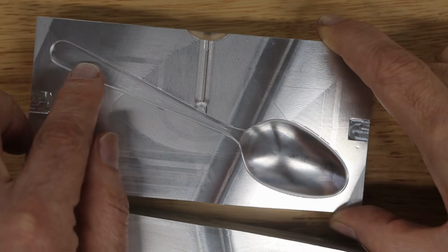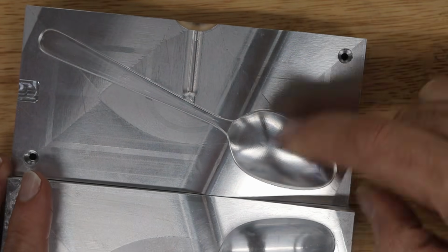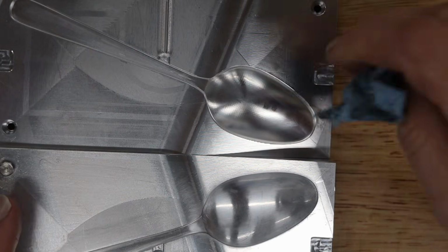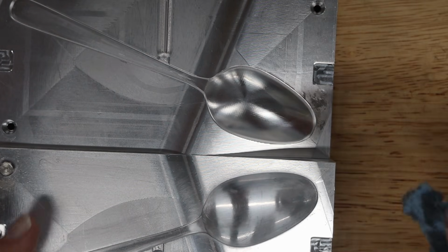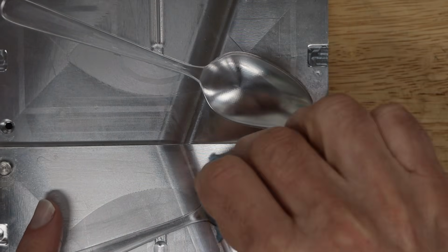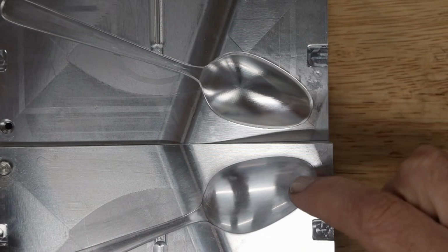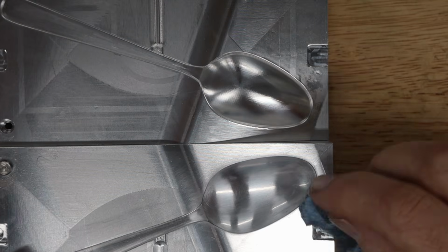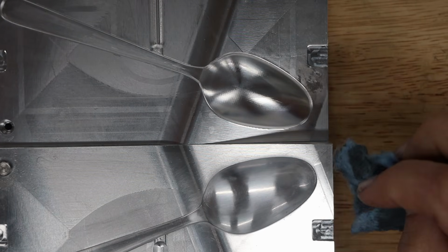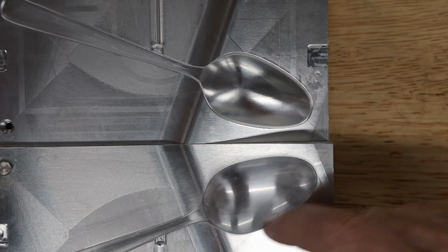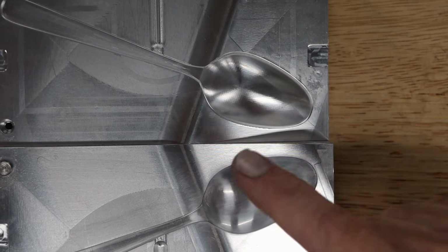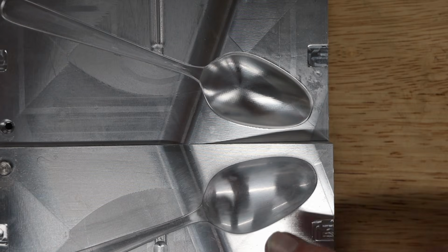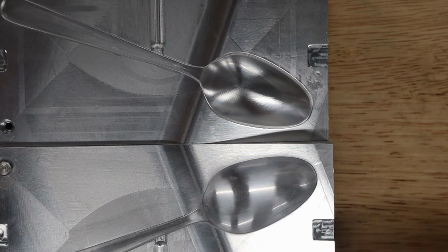The tool marks, of course, are not that bad here, but they're more noticeable on the spoon portion. And so it doesn't take that long, as you saw, to get rid of the tool marks. The request was to eliminate the tool marks, not to polish the molds, so this finish should be plenty good enough. I mean, it's starting to look close to polish because it's 4,000 grit. But it isn't actually polished, because I would take that up to an even higher grit, and then it would